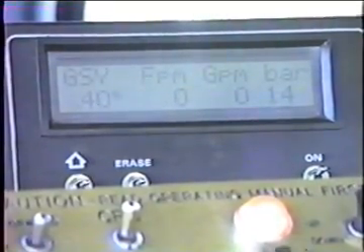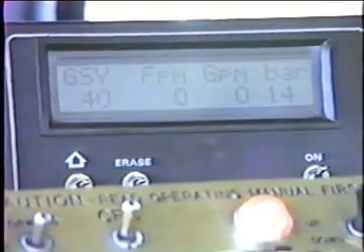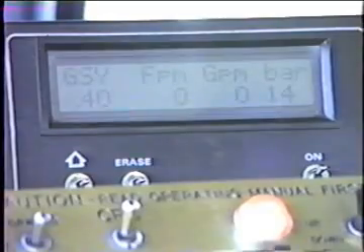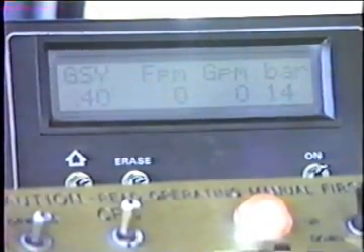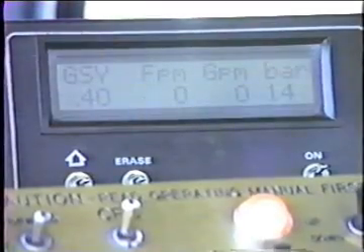So if you're at a standstill, it won't spray at all. Exactly. If you come to a standstill, and I'll demonstrate that to you, it sees all the numbers. It sees we need 4/10 of a gallon to the square yard. It sees 0 feet per minute, because we've come to a stop. It sees the bar width at 14. It calculates those together, and since there is a 0 in there, anytime you multiply or divide, which all these computations are, it sees a 0 on feet per minute, and the spray stops.